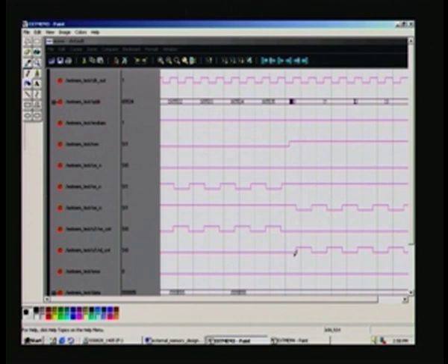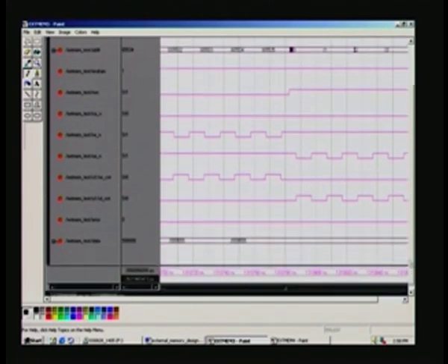And once again you can see that the write counter has been running in support of this write pulse. Now this also is stopped here, and instead the read counter is activated here, which aids in generating the OE bar signal here, and there is no change of data because it is continuously reading the same data, and you can see huge time has elapsed, and for 65535 locations we have not only written 555 data, but also cross checked, and you can verify whether there is an error.